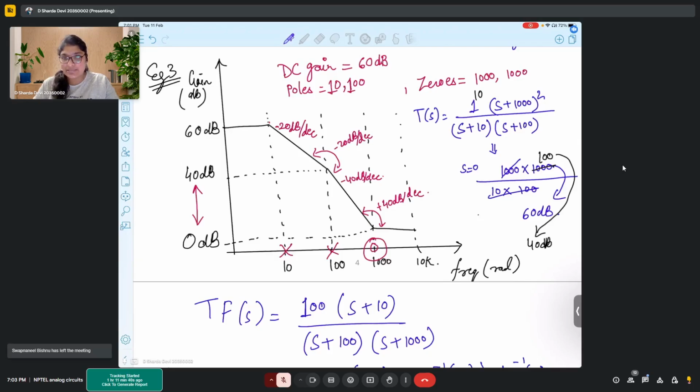most probably there is a zero present, right? Initially, the slope was not starting from 0 dB straight. It was starting with some slope from the origin and increasing, ma'am, till WP3. It doesn't mention any slope, but it was increasing with plus 20 until WP3. There are WP1, WP2, WP3. At WP3, the slope was 0 dB, ma'am.